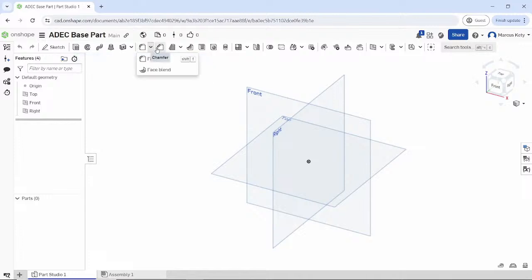And then you have chamfers here. We use lots of those to break edges, because edges are weak points when you look at parts. They're stress concentration points. Drafting is something you won't use a whole lot of. Ribs you may use, although you could make them with an extrude. Shell you may use if you're doing some kind of modeling and you want it to be accurate to what your physical part is, with 3D printed parts typically being hollow, but you probably won't use it here.